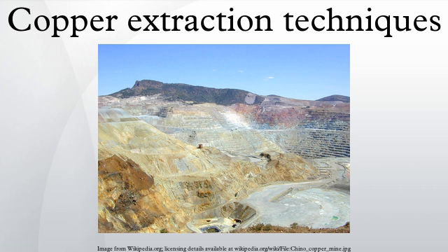These skimmings are generally subjected to a cleaner scavenger cell to remove excess silicates and to remove other sulfide minerals that can deleteriously impact the concentrate quality and the final concentrate sent for smelting. The rock which has not floated off in the flotation cell is either discarded as tailings or further processed to extract other metals such as lead and zinc, should they exist.